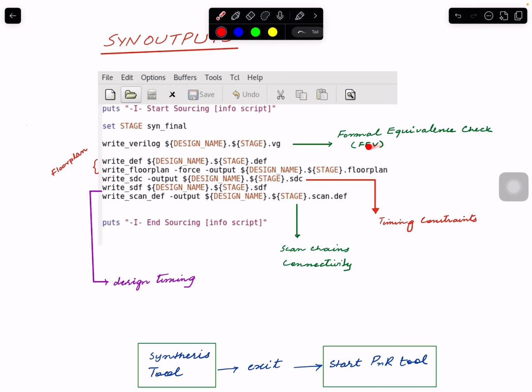So the whole check is to make sure that our synthesis output, which is the one we're going to take forward to placement, CTS, routing, then finally ECO changes and all that, and we will get that ready for GDS. For each of those stages, we want to make sure that the tool is not changing the functionality of the input design or input RTL. Makes sense?